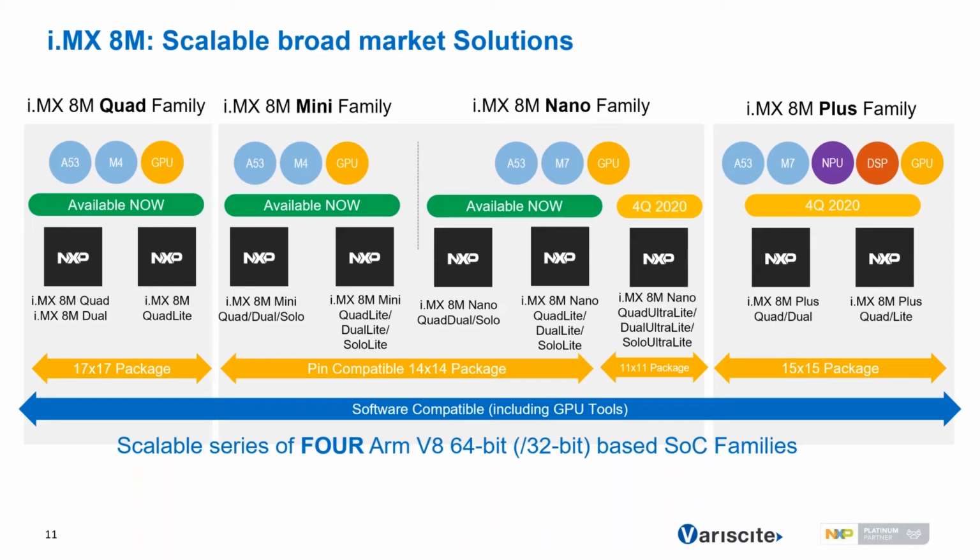The 8M Plus maintains the same 14 nanometer FinFET process node, but takes the next step in that processor development by adding a dedicated neural network accelerator, and integrates a DSP and an ISP to enable a range of machine learning and artificial intelligence usage models with low latency and power.